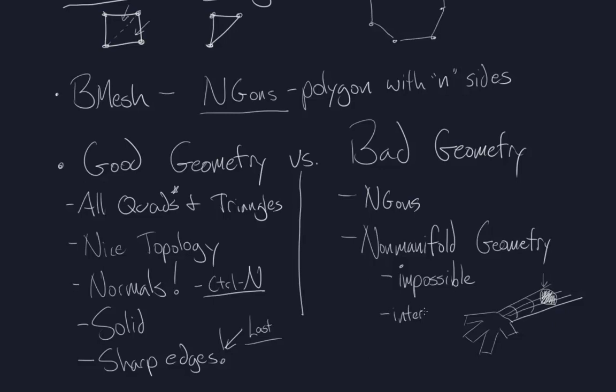Particularly, say you've modelled the hand separately and then attached it later. Yeah, and then forgot to delete the face before the reverse. Right, so what Gavin just said is if you are modeling things separately and then reattaching them later, you can really run into this internal geometry problem. And you definitely want to keep an eye on that.